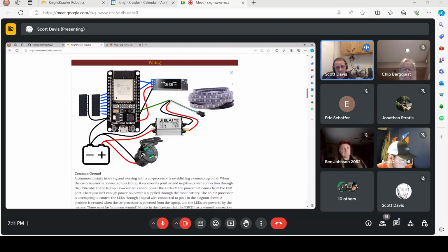In our case this year, we had 4 open spots on our DIO rail on the RoboRio, and that gives us up to 16 different light modes. So that's more than enough for what we were trying to accomplish, and I think that's probably pretty similar for a lot of teams.